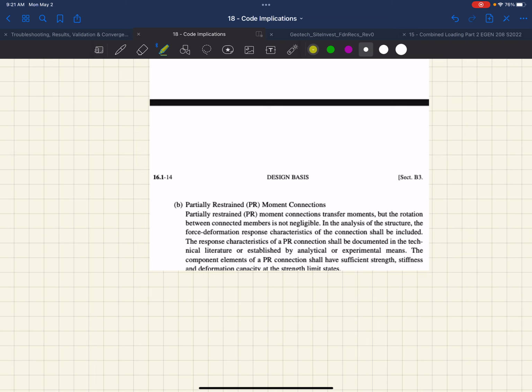There's some literature attached to it. I'm sure there's some research on different connection configurations. I was going to say, is there research on that? Yeah, there would have to be. Proprietary? Yeah, if you look at it from a mechanics sense, right? You have this node that has the stiffness of the column and beam all framing into one node, right? If these stay fixed and this rotates, you could figure out what that stiffness would be. It'd be essentially the stiffness of that beam bending, right? So you could come up with some stiffnesses and rationalize it some way or another.